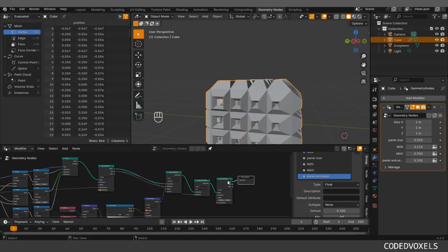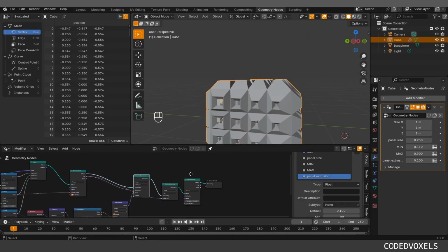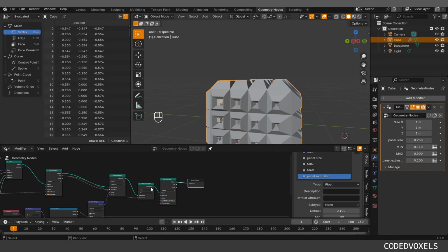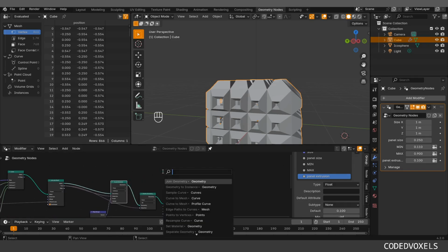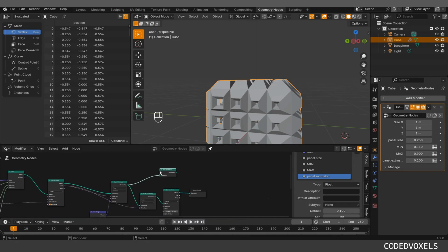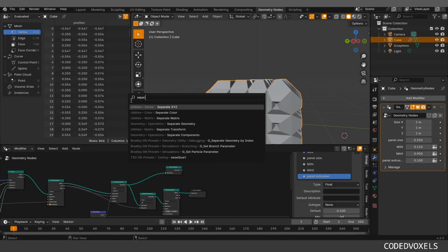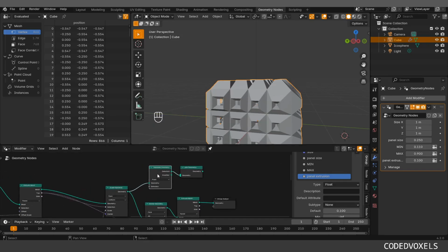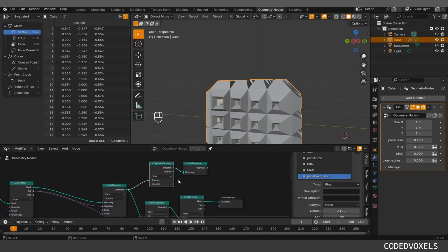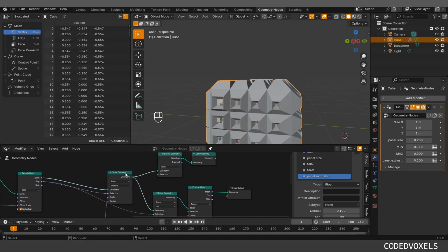So what I'm gonna do is, I think if we go back to these scale elements, we have that geometry before we extrude it and scale it. So I'm gonna take this one here, use the join geometry node here. We'll first separate geometry, and I'm gonna separate that initial part, the opposite of what we had before.